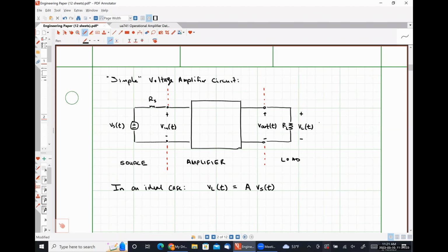So do we have anything exciting in this system? No. So that means we're not going to see a voltage or anything like that. So if we're dealing with a Thevenin equivalent circuit and the voltage is 0, what's that leave? A resistance. So we are going to have some input resistance that is characteristic of everything to the right of these source terminals. Okay, so that's the first part of our practical model.